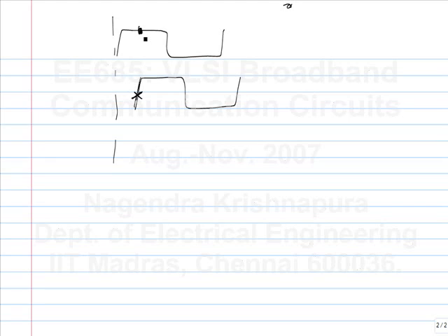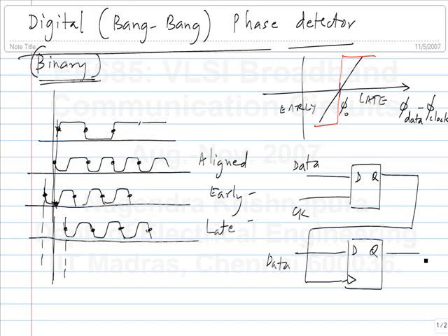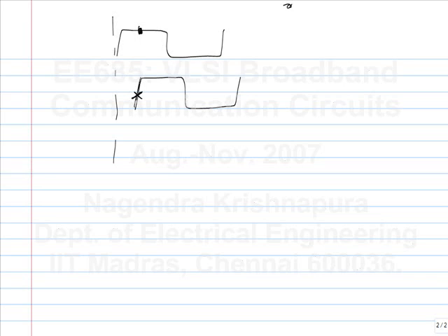Yeah, so maybe the delays in the system will make it a little off. The only issue is some clock to Q delay here. So Q is not aligned with the clock very well. Okay. So that will also work. So some of these things I have not seen myself. So maybe you can investigate it and see how well it works, etc. Okay.